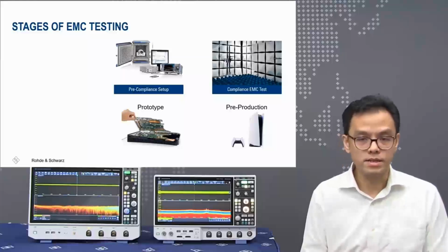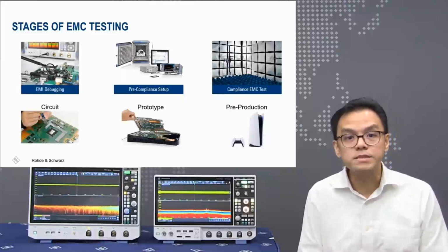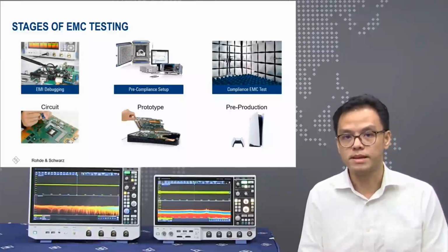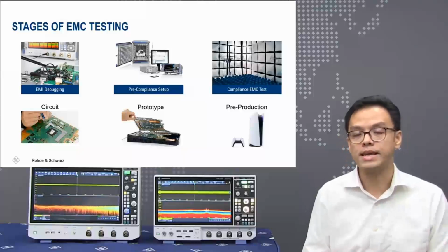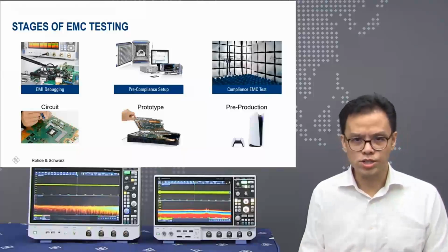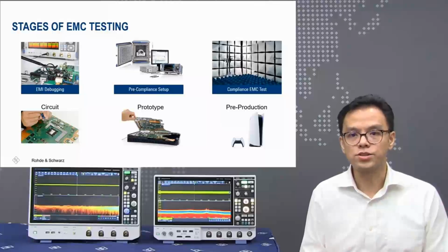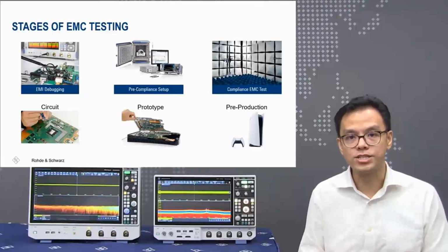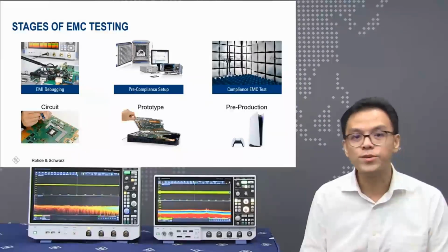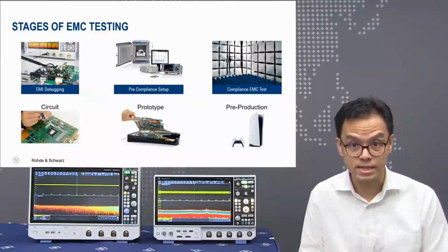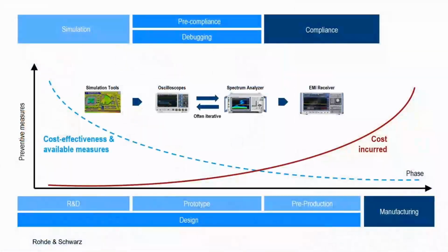Moving one step further, EMI debugging is becoming more and more common, especially for power-related circuits. Solutions to resolve EMI issues often involve the addition of capacitors and chokes, which occupy PCB real estate. Hence, it's advantageous to address these issues during the early design phases.